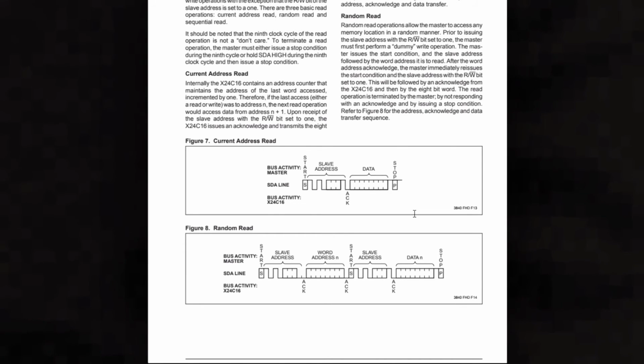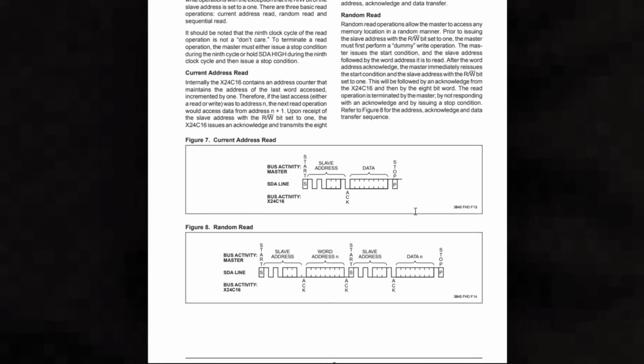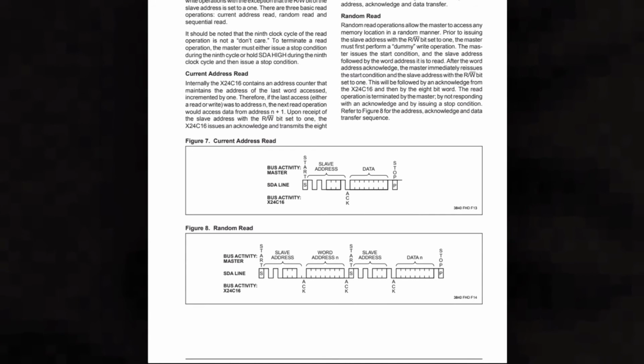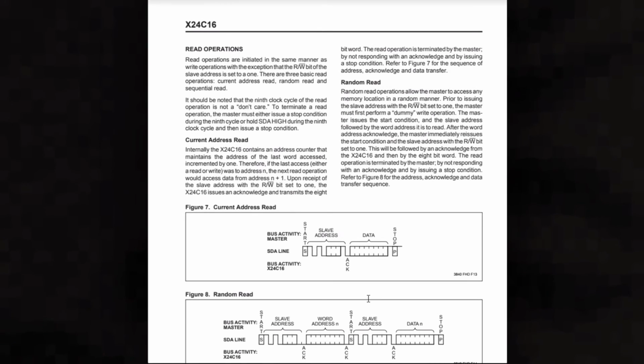This is a little confusing because the 4 bits of the device address 1010 are still followed by the bank address. Only the word address is recycled from the previous write call. I suppose I'll have to investigate this at some point.